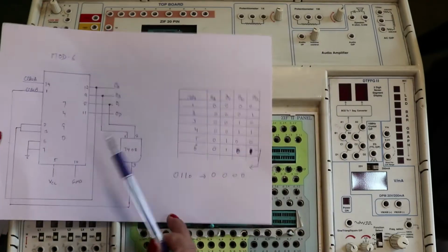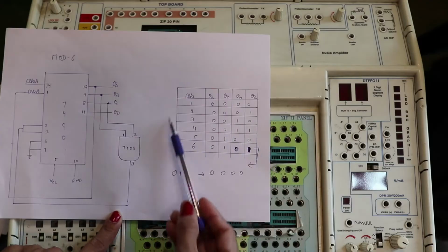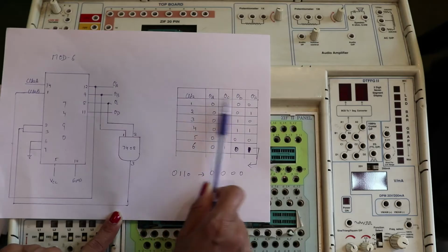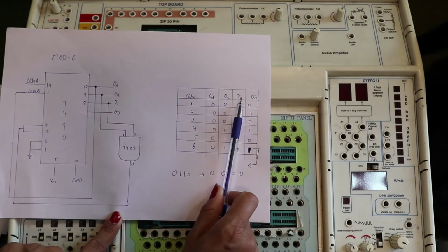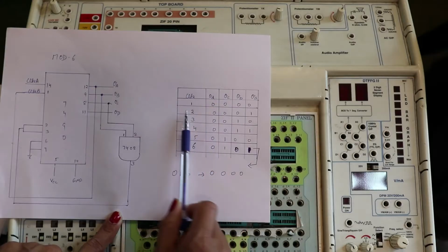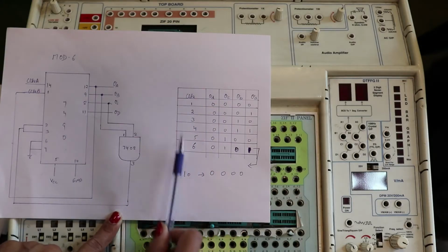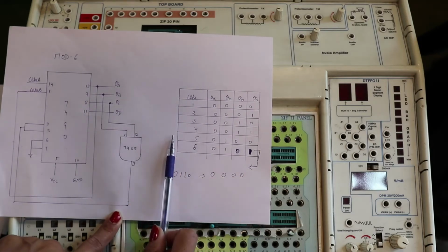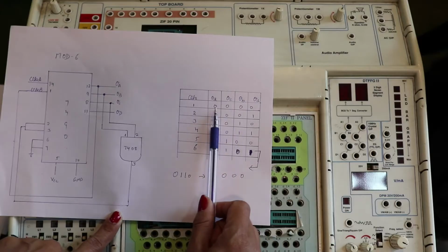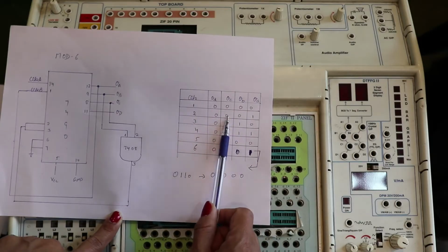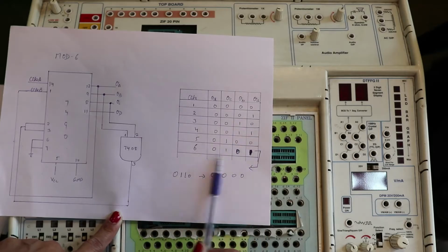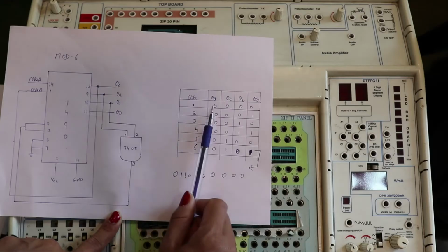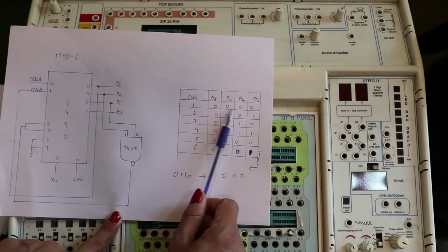So first we check the truth table for MOD-6. Here is the clock pulse, and we are going to show the outputs QA, QB, QC, QD. The counter is going to start from 1 and move till 6, or either 0 to 5, and the counting starts 0 0 0 0, 0 0 0 1, till the 6th value, and after this 6 it is going to return back to the first, that is 0 0 0 0.